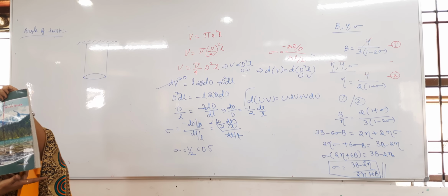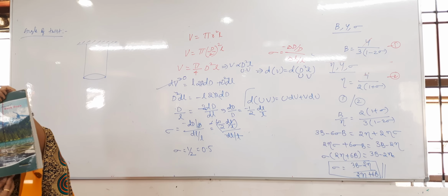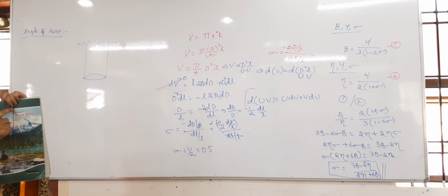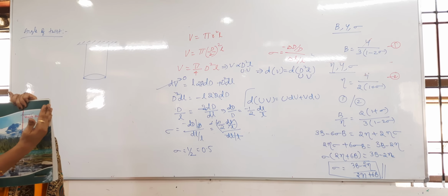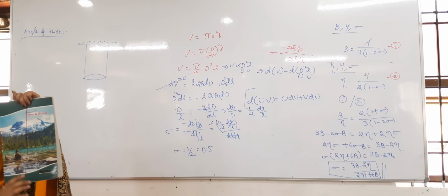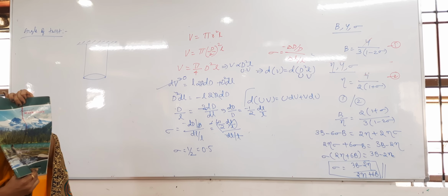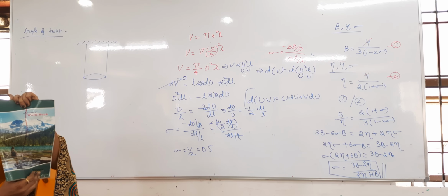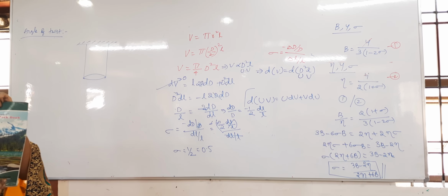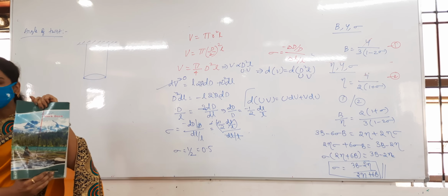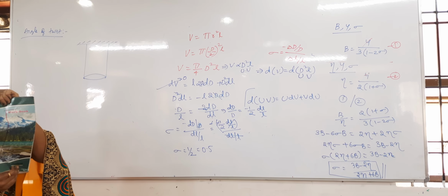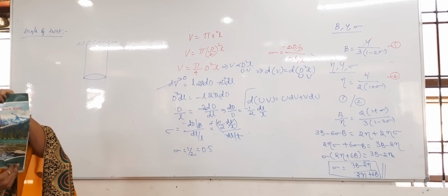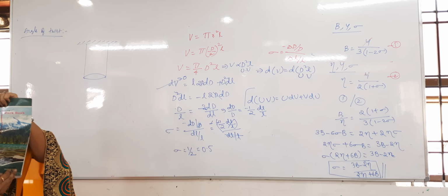That is also twisting by some angle. That is the twisting angle, and the upper one is the shear angle. See, this line will move a little bit. The line was like this before; now whenever I twist, it displaces a little bit. So only a very small strain will be produced. In case of shear strain, I said, it is always very small. So a very small shear strain is produced at my hand, and at the right hand, what is happening? Angle of twist is produced.